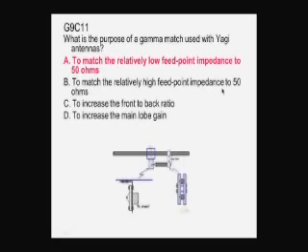Let's take a look at what a gamma match looks like. I hope this drawing will be meaningful to you if you haven't actually seen a gamma match. Here's the driven element of your Yagi right here, or a section of it. It actually extends out farther than this on both sides. The square thing right here is the boom of the antenna. So we're looking right straight down the boom of the antenna. Here is our feed point.